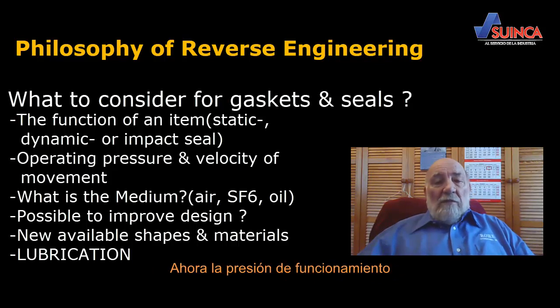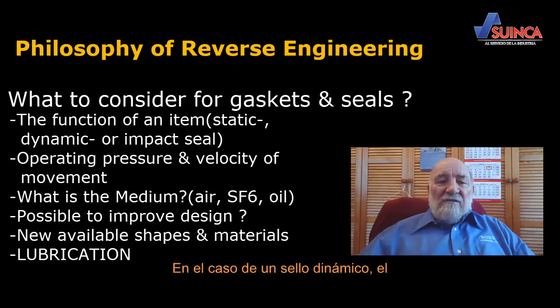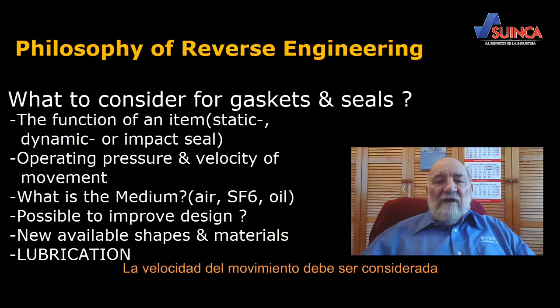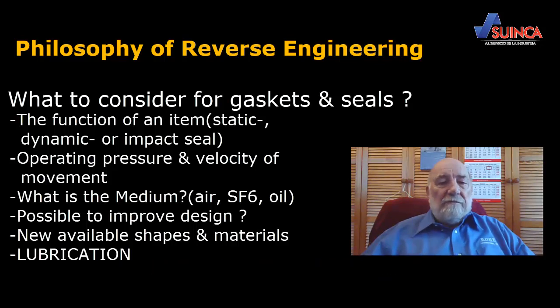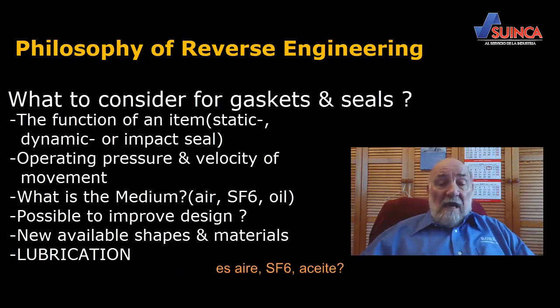Now, the operating pressure needs to be considered. In case of a dynamic seal, the velocity of the movement has to be considered. And then we have to consider, what is the medium we want to seal? Is it air, SF6, oil, other gases?